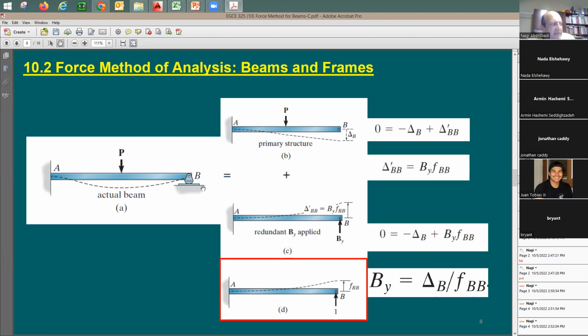So what I'm doing here is, let me take this beam and split it into 2 beams. You're with me? Yes, okay, I'm going to have these 2 beams. So this one is going to be equivalent to this beam plus this beam. I'm going to take the first support on the right, take it out, remove it for now. I'm going to put the same point load right there.